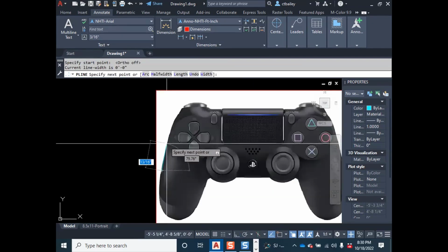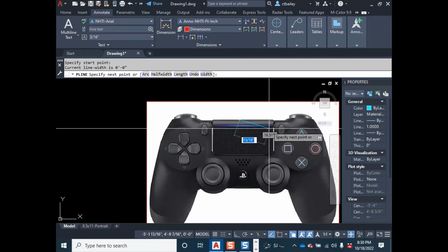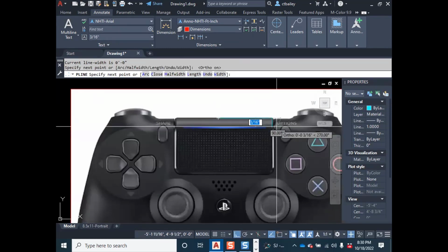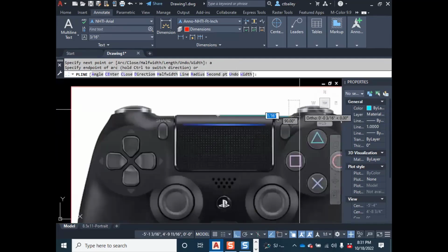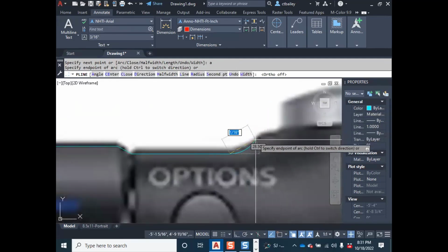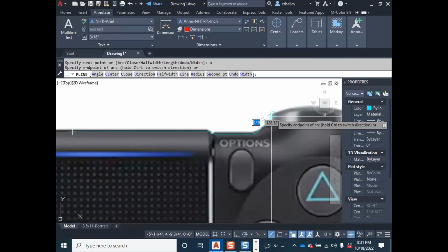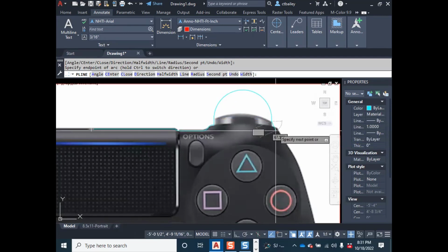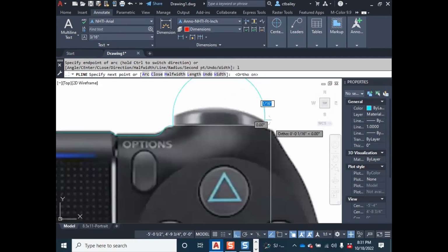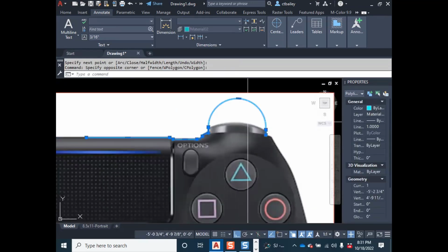Okay, so I've got to find a tangent. Let's start up here. Let's find a tangent from the midpoint. F8 there, F8 down, F8 over. Now I can go into arc mode, get out of F8. There's my arc. There's another arc, line, arc. Now this arc is going to be totally whacked because it's not tangent, right? So click there, line segment down, F8 on. So hold there, go back to your arc segment that's totally bowed out, grab it, and just eyeball it.